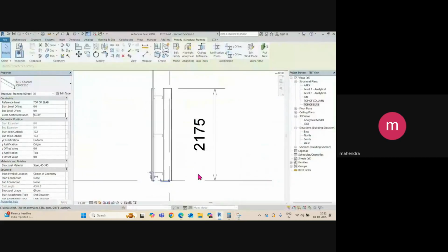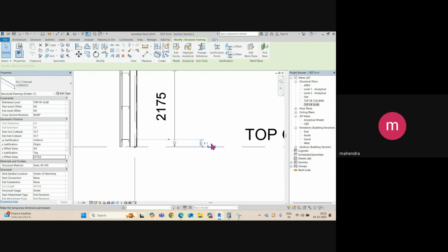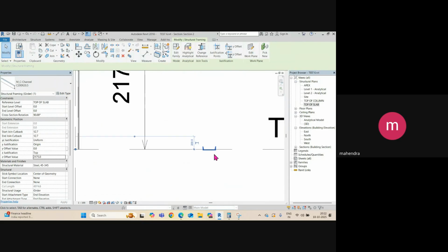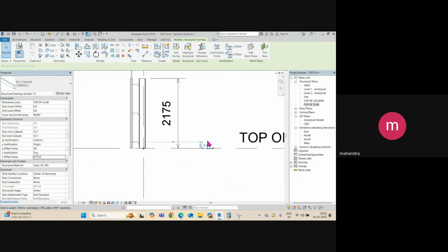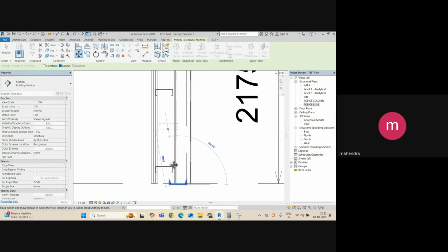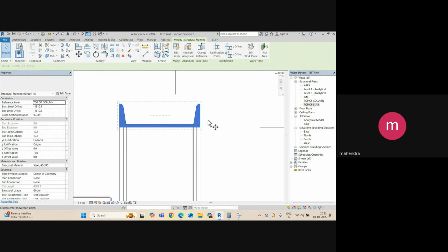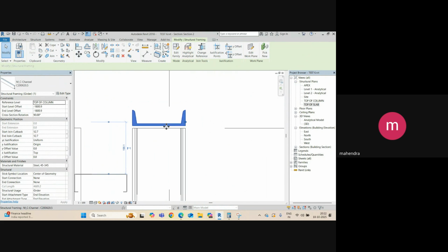So you need to select, and you have the Z option, so you can add 2175 here, right? So where does it come, oops, what happened? Z offset, right, comes here. So I think 90-degree angle. Okay, so Z is wrong. Select here and just move, and you can place it here, like that. And you can move it by 10 above if you give the welded connection.